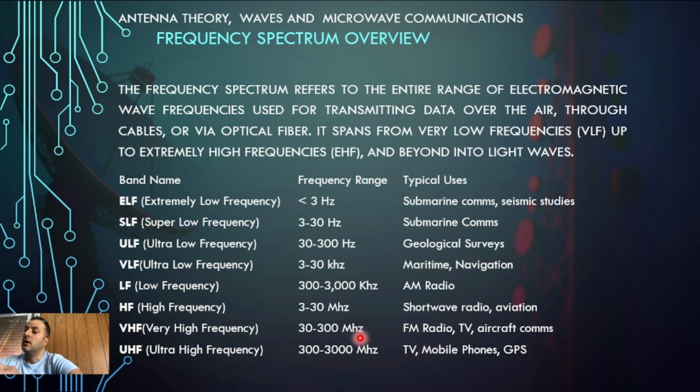All right, so for higher frequencies, you can carry higher capacity, but the range would be shorter. That's the difference mainly between longer frequencies or longer waves and shorter waves. Shorter waves have higher frequencies, so they can carry higher capacity for data, but longer wavelengths, lower frequencies, they have higher penetration. They can go through thicker obstacles, so their range would be longer or greater.